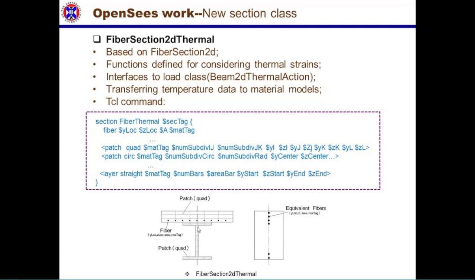We have the 2D fiber section, and you define the fibers, bring the fibers in, and like the concrete section, you could use the patch commands to define the fibers. But in the 2D analysis, it works just because we ignore the Z coordinate, so it works like equivalent fibers along the y-axis.